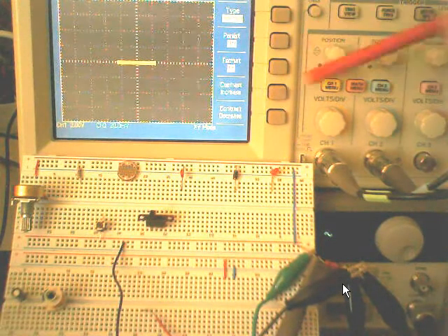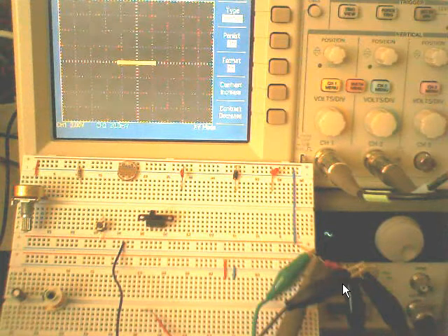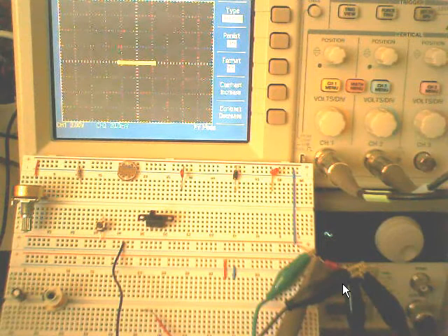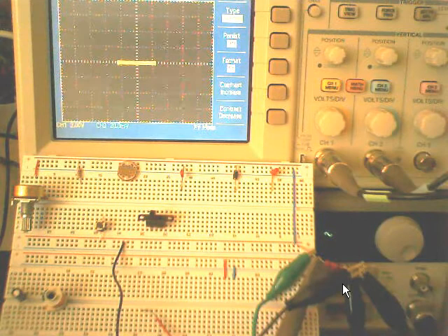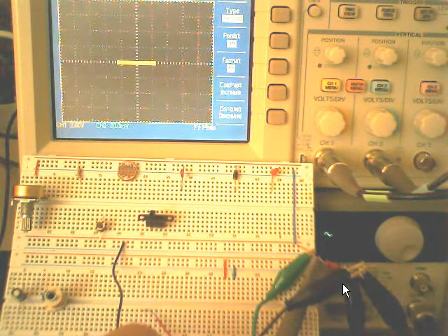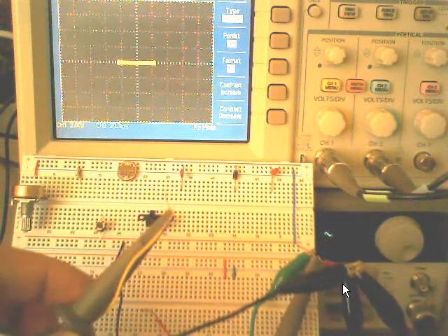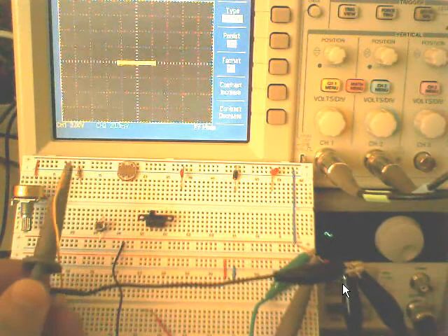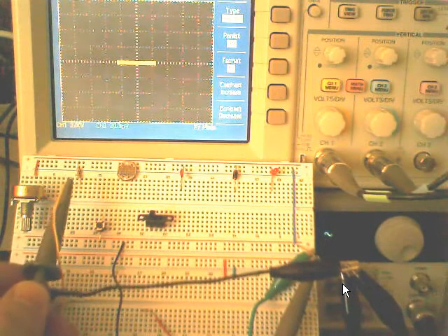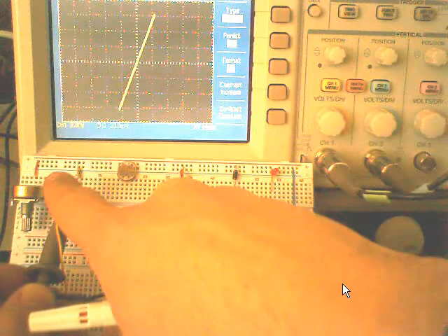This is a device called an oscilloscope. It's mainly used for the VT graphic of components. You can see the voltage with respect to time. But for this purpose, you can use it to show the IV characteristic of components. I will apply some signal on components and show you the IV characteristics of components.